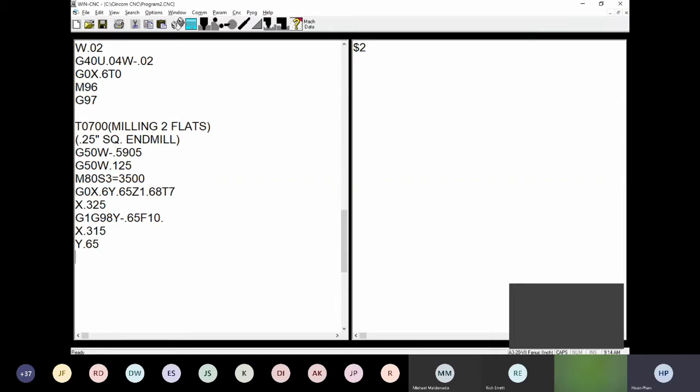which is we can flip it over 180 degrees. So one thing right here, we didn't engage with the Z-axis, so I can go back here and then input the argument that we command, like we talked about yesterday already, which is the E. So right here, it will index the tool number 7 and also tell the machine to lock the main spindle at 0 degree. So right here, if we have E right here,